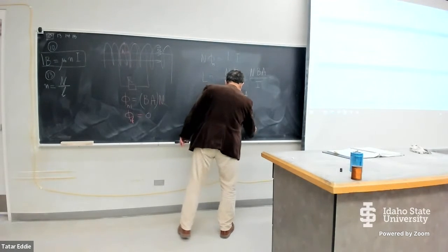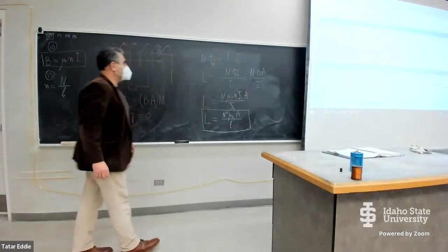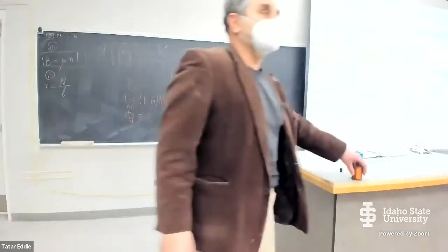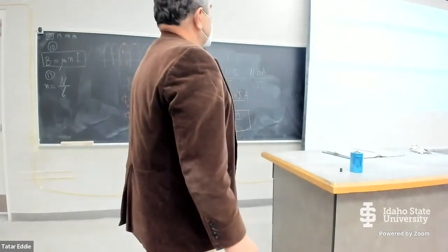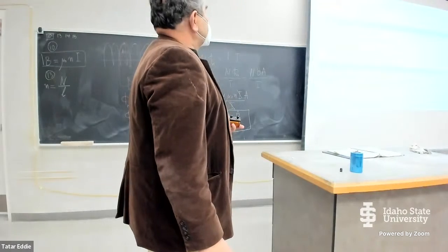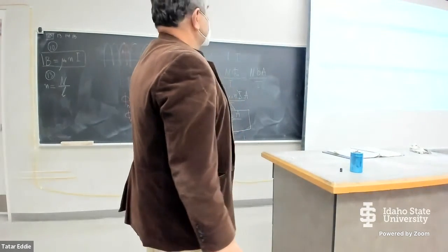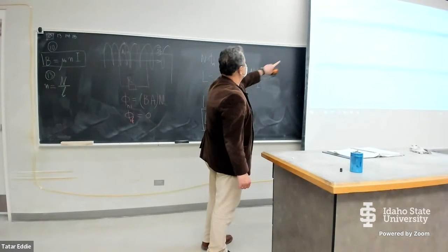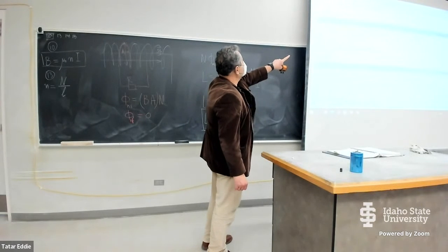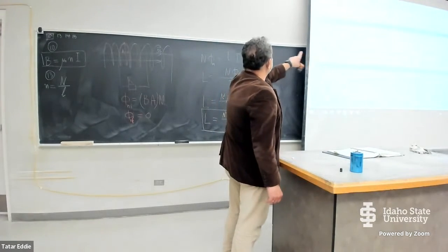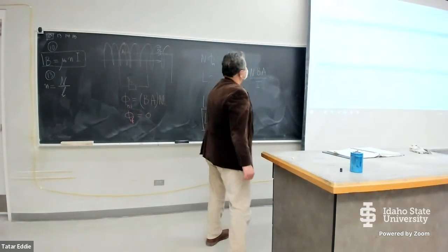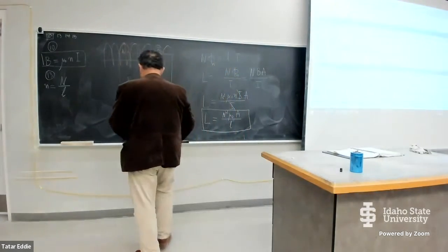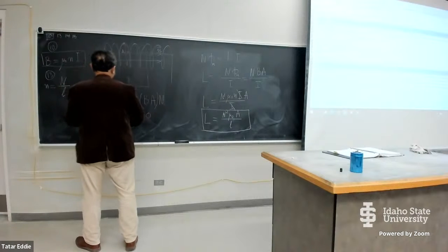So this is the formula that gives you the inductance of a cylindrical solenoid like this one. And for us, they want a certain value of the inductance. They give the area, they give you the length, you have to figure out N. So you have to solve this expression for N. And it is going to look like this.